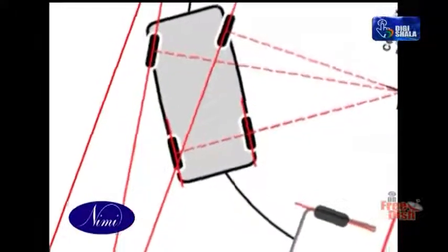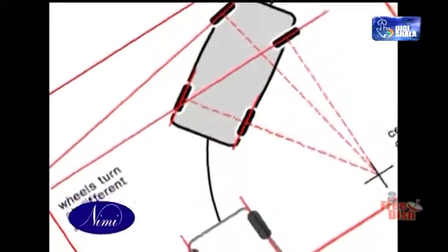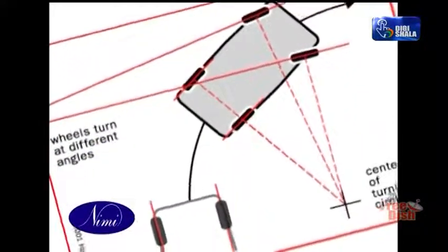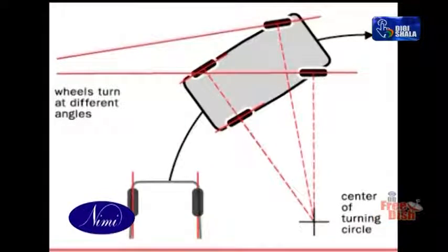When a vehicle is cornered, the inner wheel moves through a shorter distance than the outer wheel. This means that the inner wheel must slow down and the outer wheel must speed up. During this movement, it is desirable that each driving wheel maintains its driving. This task is performed by a differential.